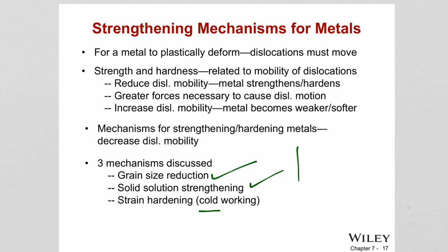And I told you guys there is this region, right? This region called the strain hardening region, because there was the strain hardening exponent. So as you see, I need to keep increasing the forces applied, because the material is getting stronger and stronger in that region, because the number of dislocations is increasing, and dislocations can be obstacles to each other. Think about so many people in one place. It is very difficult to move, right? So this is the same concept.